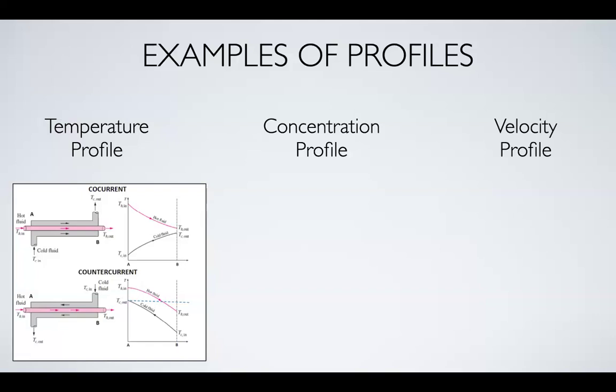This represents the energy transport, okay? Do you know what these are? A heat exchanger, right? A double pipe heat exchanger. We have the inner pipe and the outer one. If you measure the temperature of the fluid inside these pipes, you will get the temperature profile along the length. So what you get is something like this on the graph.